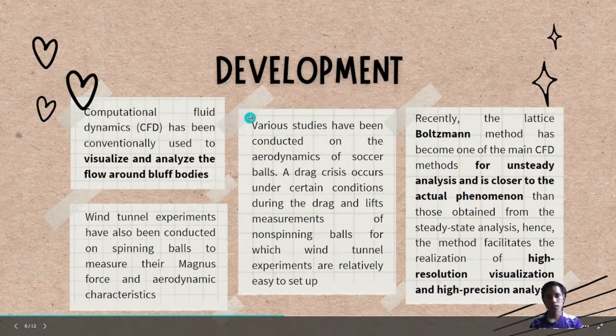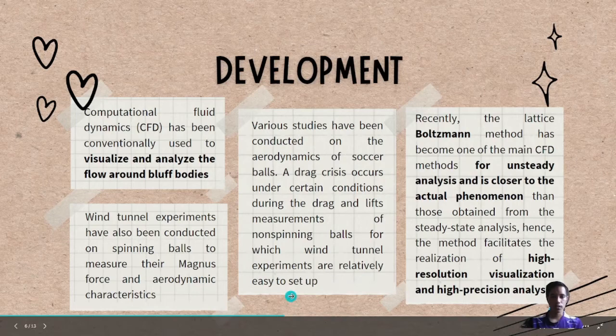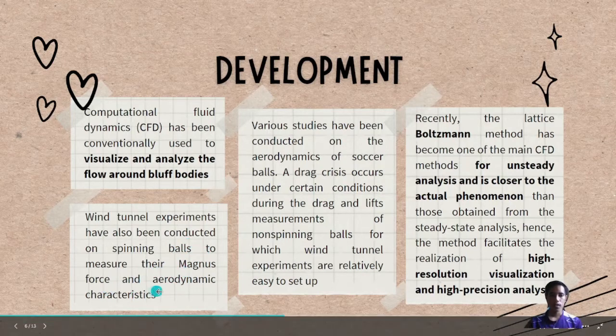In addition, many studies have been conducted on this application, in which a drag crisis occurs under certain conditions during the drag and lift measurements of non-spinning balls, for which wind tunnel tests are relatively easy to set up. Wind tunnel tests were also conducted on spinning balls to measure their magnus force and aerodynamic characteristics.